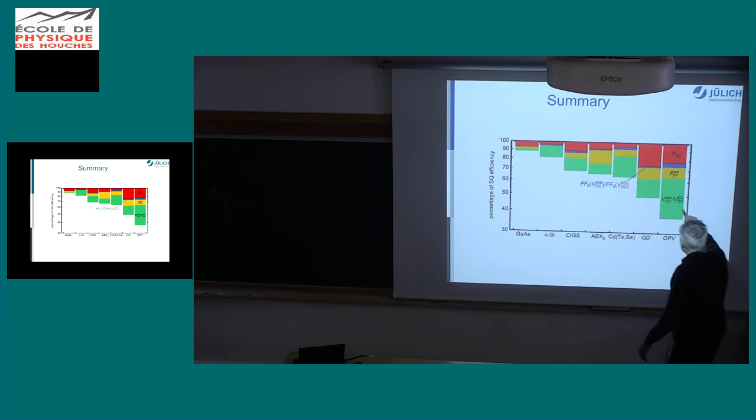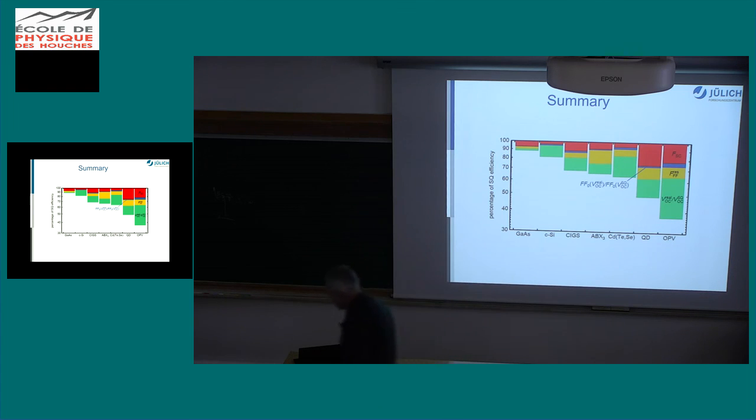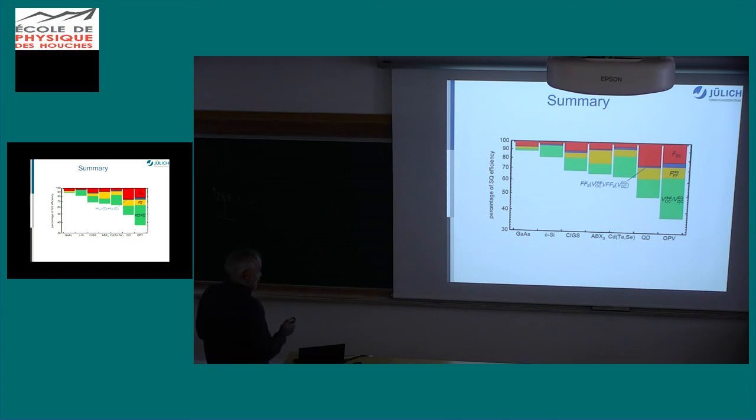Then derived from that one, there is this small blue thing that's just a consequence of these differences. So if you change VOC, you also change the fill factor. That's why we're having the blue. And then you have the fill factor losses, which mostly come from resistive properties.